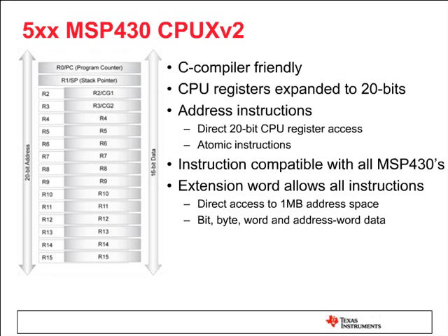So it is fully instruction compatible with all previous MSP430s. If you learned the instruction set before, you know the instruction set now. There's really nothing different about that or incompatible with the previous devices, meaning if you have an existing 2-chip solution, let's say you have a 2274 and a CC1101, then most of that code is going to be applicable here, which I think is nice.